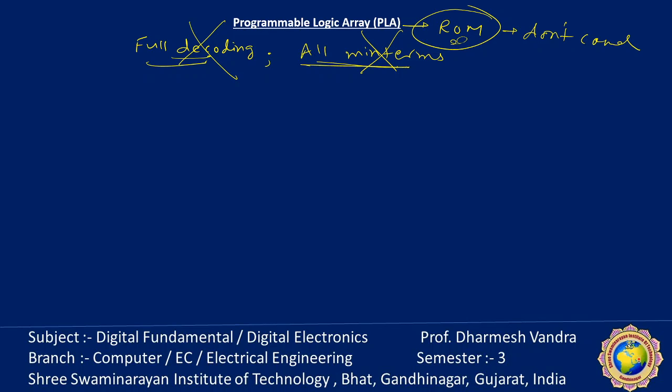So in the PLA, the decoder is replaced by a group of AND gates. Let's see one example of how the internal diagram looks. The PLA is a group of AND gates, each of which can be programmed to generate a product term. The product term is also in the hands of the programmer. The AND and OR gates in the PLA are initially fabricated with links among them. The specified Boolean functions are implemented in sum of products form.